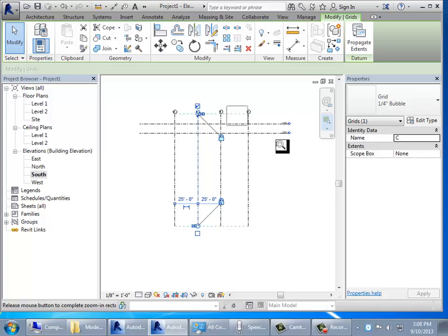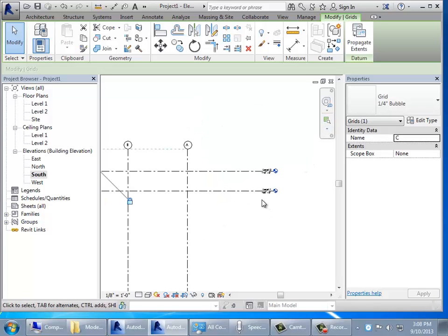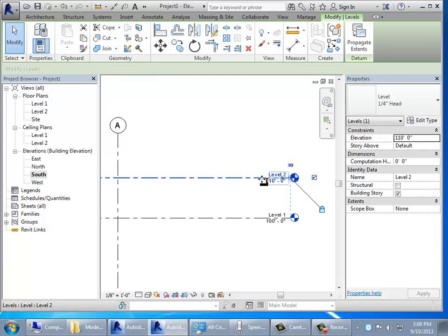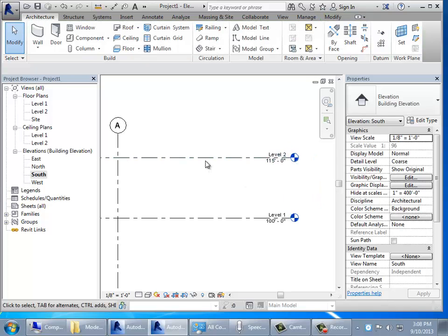Now, I don't know about any buildings you've seen lately, but 10-foot floor levels is really pretty uncommon in anything commercial. So you're probably thinking about 12, 14, 15 feet, something like that. So maybe make those a little bit bigger. Otherwise it's for midgets, because we could walk through that building, but there's no room, no ductwork. It's a hobbit house.